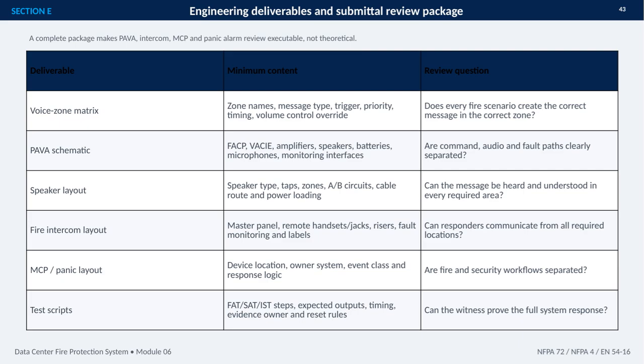Speaker layouts need enough detail to verify coverage, intelligibility, circuit redundancy, cable routing, and power loading. The package also includes fire intercom layouts, so responders can communicate from every required location, plus MCP and panic layouts that distinguish fire workflows from security workflows.